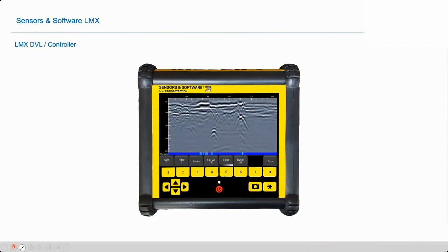So we're going to pop into line view settings, and if we pull the radar back, a little radar appears at the top of the screen and a line appears on it with a cross on. We can move this cross up and down to measure the depth of our hyperbolas, and we can do a hyperbola calibration by bringing up this virtual hyperbola, which I'll talk about more later on.